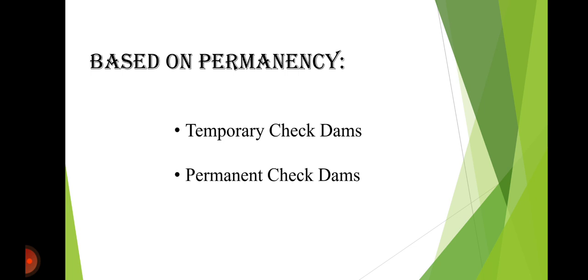So, brushwood check dam is made from branches, brushwood and wooden stakes, suitable for small gullies and low runoff. Usually a temporary structure, it helps reduce flow velocity and trap the sediment.